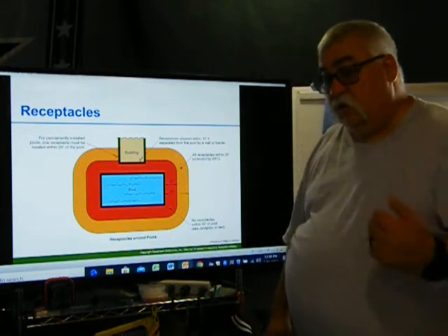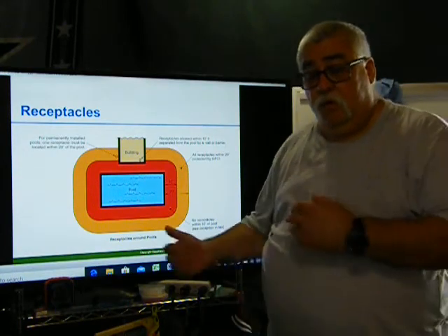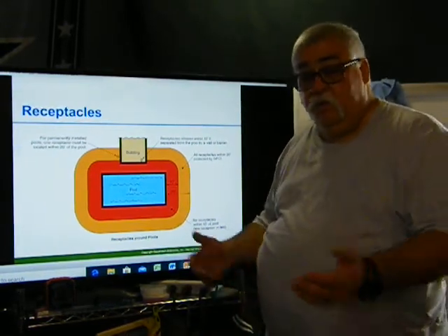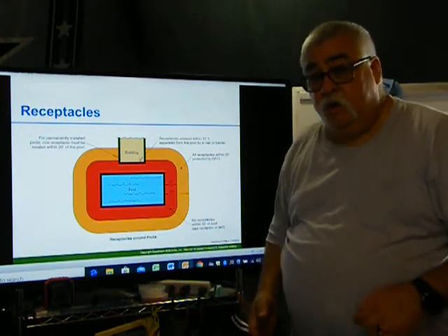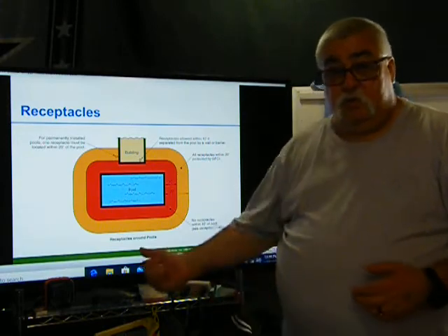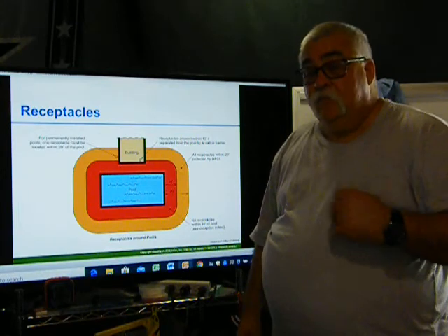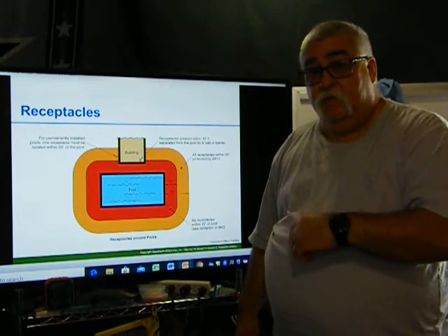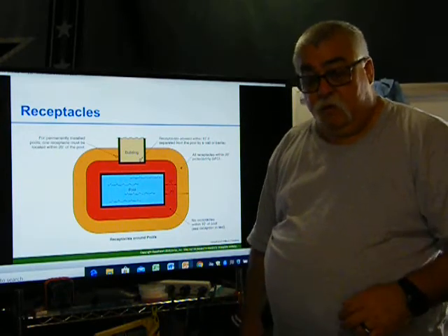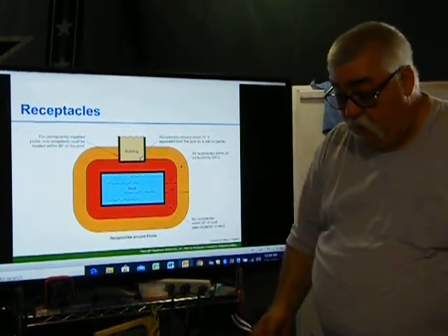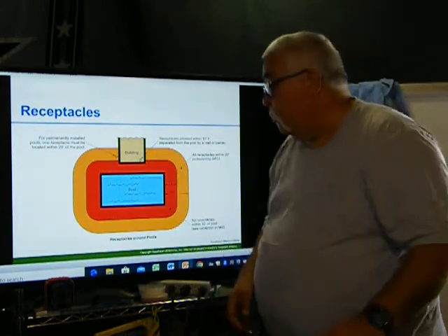You know, you always run into this having equipment outside. You have to have a receptacle close to the equipment. Why? It has to be within 25 feet. So that way if they're servicing that piece of equipment, they can plug in whatever they have without having to disconnect what they're working on. You know, say they're trying to test run, but they're trying to use something. It's the same thing with a unit in the attic. You have to have an outlet, a service outlet. Besides the power for that unit, you have to have a service outlet, so in case you need power to plug into, without having to unplug the appliance. And it might have a switch or whatever to turn it off, but you have to have a separate outlet so they can work on it.